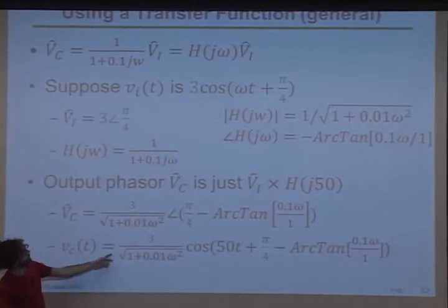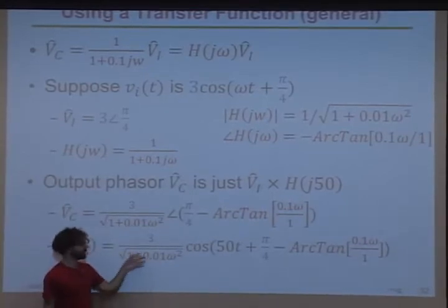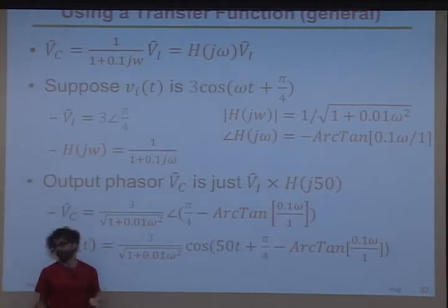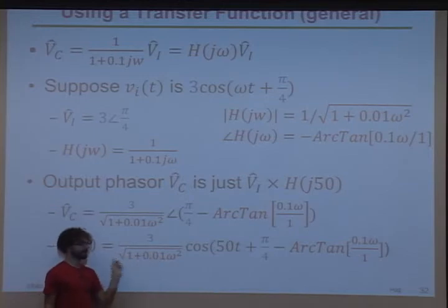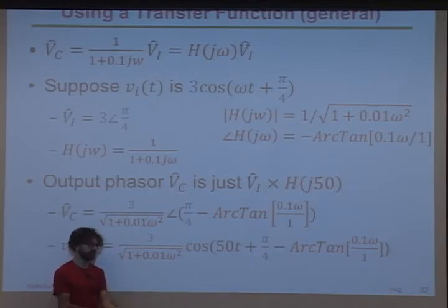So if you'd like, the scaling factor, this red number, is how much it scales by. The biggest it can be, because it's a passive filter, is 1. So when omega is 0, it's just locked in where it started. And as omega gets bigger, the cosine is less and less able to show itself at the capacitor, right?